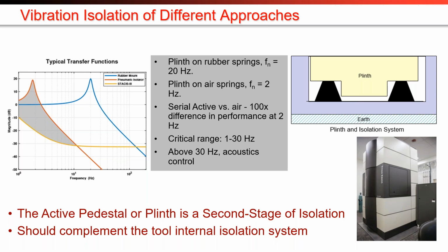And you can see there that at about 20 hertz, which we've chosen as a typical frequency, you get about an order of magnitude amplification. And it starts to isolate above 30 hertz. But by those high frequencies, they're really not such a concern. So that's actually amplifying more than isolating in the critical frequency range, and probably going to make most problems worse.